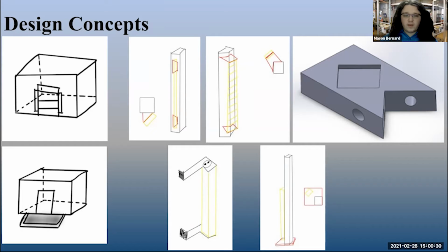Along with that, we have one cell that needs to go all the way around the lab space. So we need to have some mirrors to redirect the light curtains. We're running that through 45-degree mounted mirrors, some top and bottom brackets, an outside column mounted mirror, or some floor mounted mirrors. Next slide.